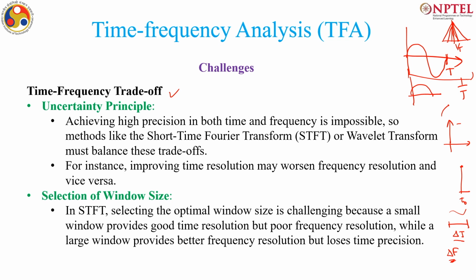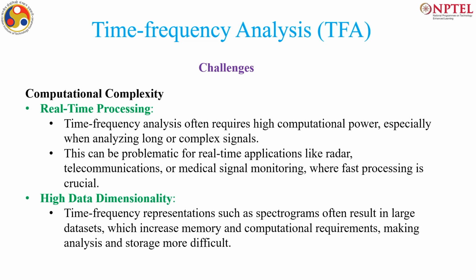So, that is the uncertainty principle, which makes the selection of window size very critical, because what is a good window, so that I get an optimal resolution in time and frequency. Another is complexity, because calculating 1D vectors in time domain or frequency domain is easier than dealing with matrices, and this will give high dimensional data, the spectrograms.